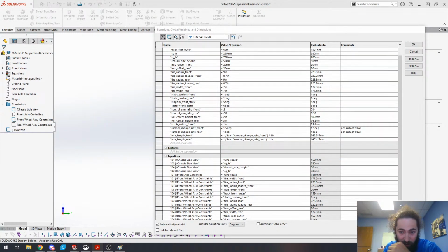So actually I have RCVD open here. I'm going to really quickly see if I can find that equation. Should be pretty quick to find, hopefully. Yeah, so it's on page 615 within figure 17.9. Camber change rate equals inverse tangent of 1 over the front view swing arm length.